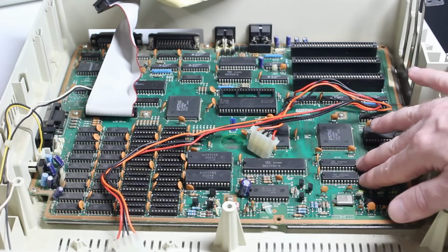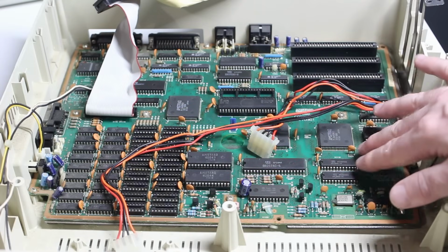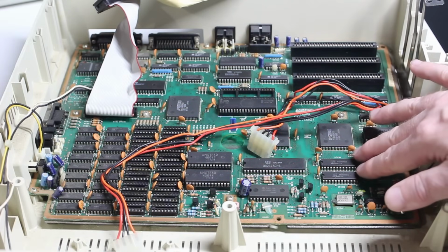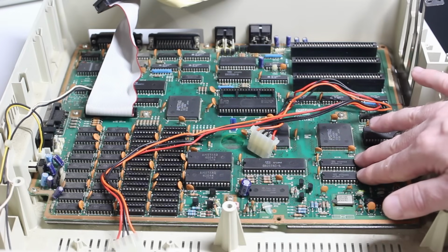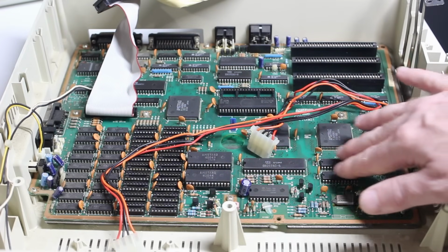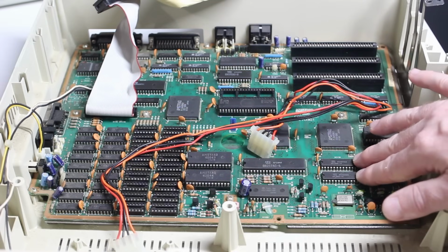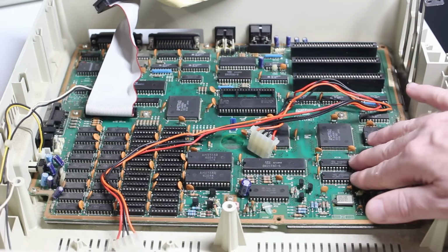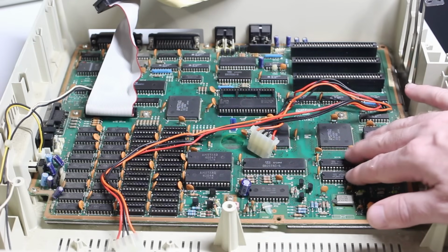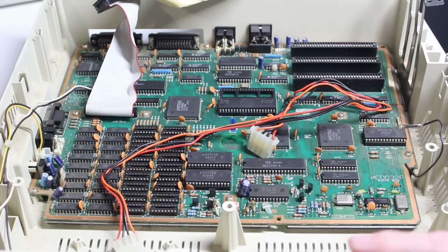So they're 64 kilobits by 4 bits each, and so if you have a pair of those, that will be 64 kilobytes. And that's actually 4 times the memory that you'd have in an ordinary CGA card, and that's because of that extra 16 color mode that this machine has. It's also dual ported RAM, so no snow like you get on the original CGA card.